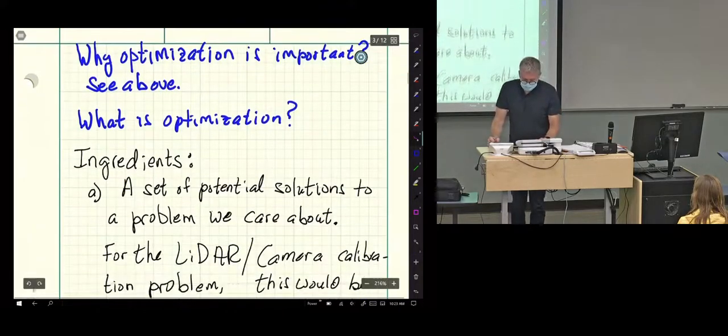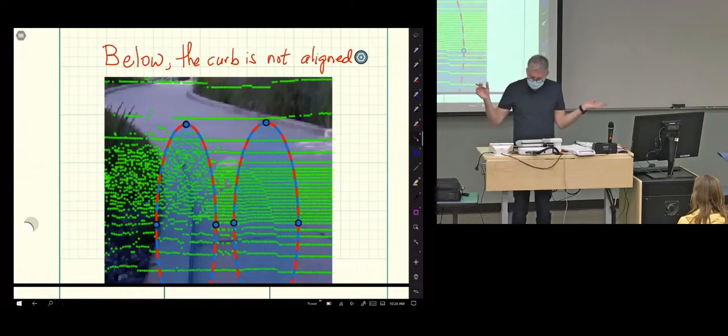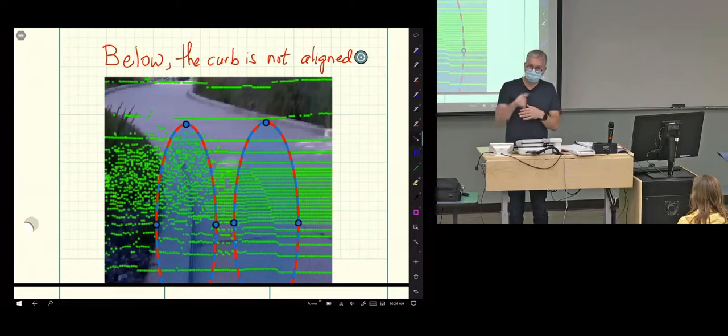But if you go through it, you'll see that it's an amazing optimization problem. It's a nonlinear least squares, because when you map the LiDAR points to the camera, the mapping to the 2D image of the camera plane is a nonlinear function. You end up dividing by distance, that's a depth, and that's what gives you focal regions of a camera. That's nonlinear. But then once you have your points down on the camera frame, you're doing least squares to line them up.